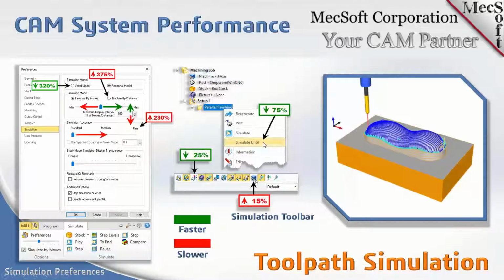Also over here, if you're in a Pro or Premium configuration and you simulate your machine tool, where you have your machine tool on the screen and you're actually seeing the axes of the machine tool simulate along with the part, just be aware that's going to tax your system another 15%, so it's going to slow it down.